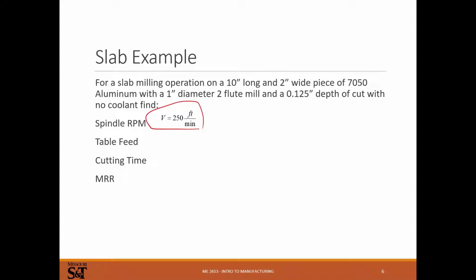Now, if you've done a lot of machining, you might know what this number means. Somewhere around 200-ish for no coolant on aluminum, if you're not pushing fast. That's a decent speed. You'll see in some high-speed machining charts for nice tooling with coolant on nice machines, 2,000 surface feet per minute. If everything's set up right, you can do that. But when I'm doing stuff by hand or on small run CNC stuff, no coolant aluminum, 200 feet per minute is pretty good. We'll push it a little faster, 250 feet per minute. Again, for production runs, you can ramp this up a lot higher.